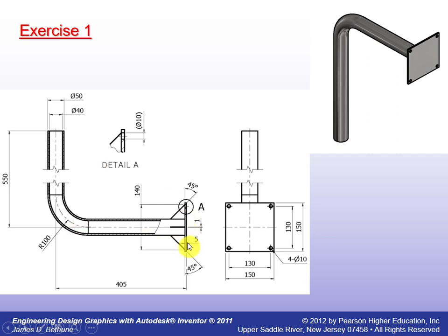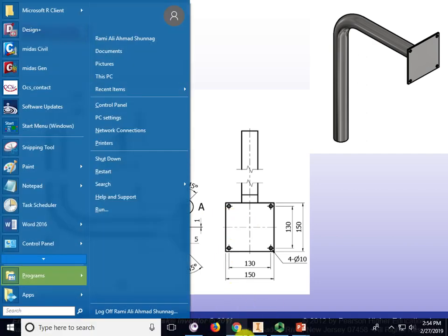Yeah, the plate. That's the plate. We can use extrude, draw a rectangle and extrude to get the plate. Then make holes, then draw a triangle or line, make the rib, and then copy the rib using pattern. And we can also copy the hole using pattern. So now I know the algorithm. Let us go to Inventor and start drawing.